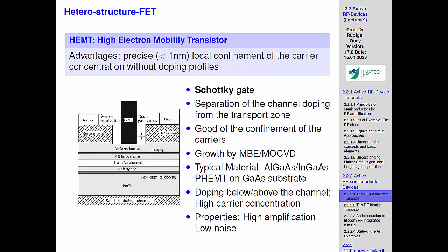We can change that distance and play with this transition a bit, and then we don't get such sharp profiles, so that we can engineer the whole story to a factor of 4, 5, 6 over silicon. So we don't have that particular hotspot. If you do this right, you can really get a large voltage swing, and for the same gate length, you get an advantage in terms of voltage.